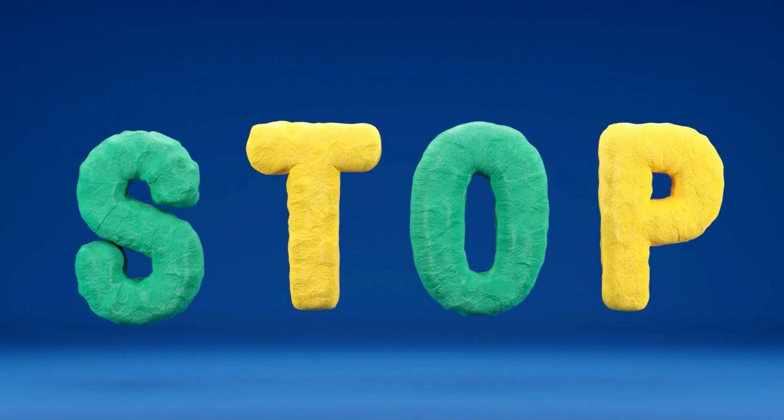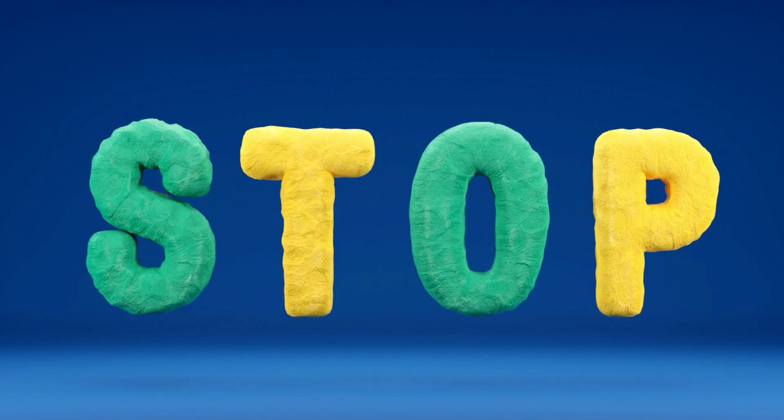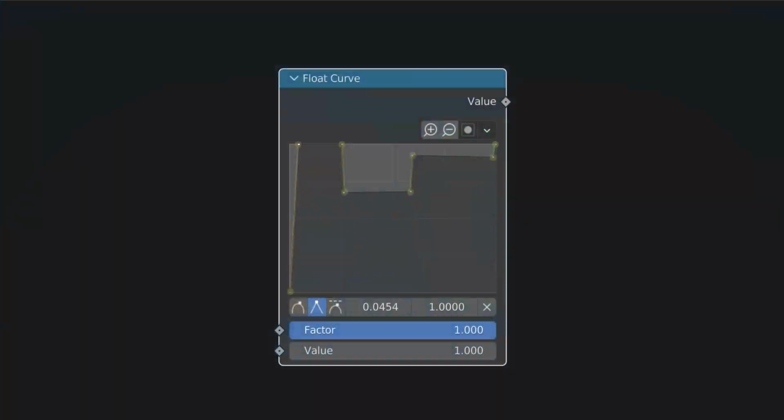So there's one thing we need to keep in mind. In order to get the stop motion effect, we want the value to jump from one value to another in a very short amount of time. Let's say here the value is 1 and we want it to jump to around 0.6 in this short amount of time. So we need to keep the graph line as close to 90 degrees as possible. It doesn't really need to be 90 degrees, but close to 90 degrees is good.